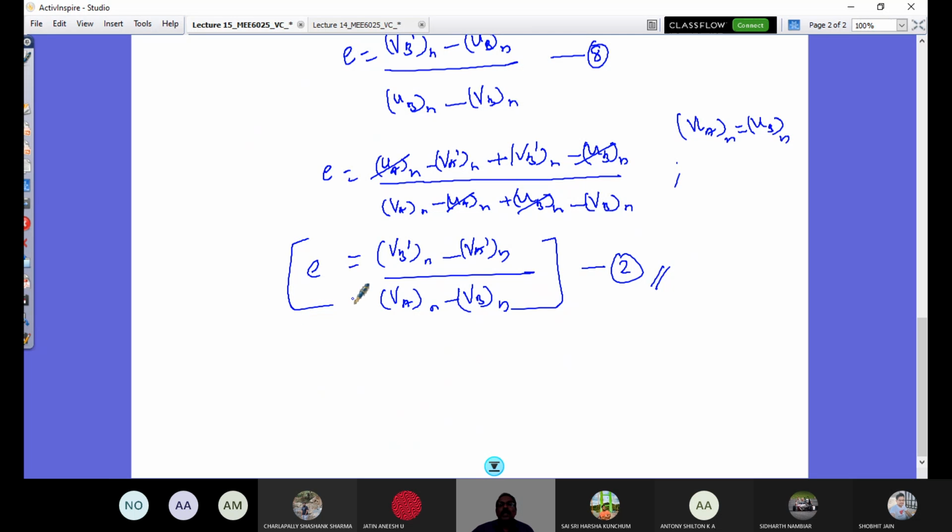If out of two vehicles, both are arbitrary, they both have some velocities as well as some angular velocities, and they collide. But if one or both colliding bodies are constrained to rotate about a fixed point, in that case it's similar to that of a compound pendulum motion. The Charpy impact machine, you see that the pendulum is hinged at one end and the other end has got a striker, a huge mass, which is lifted and then released.